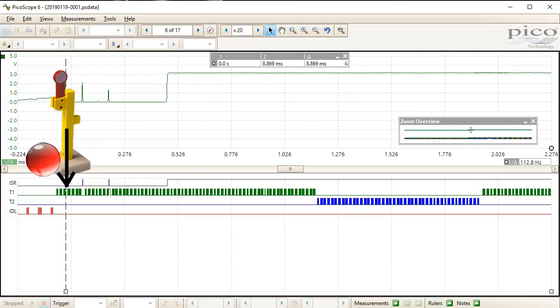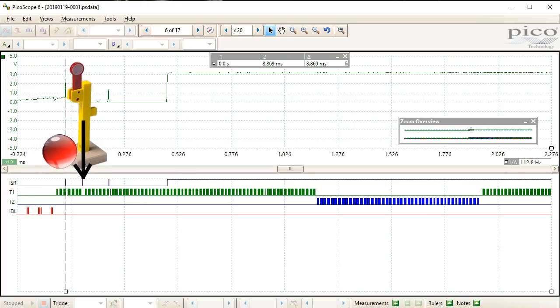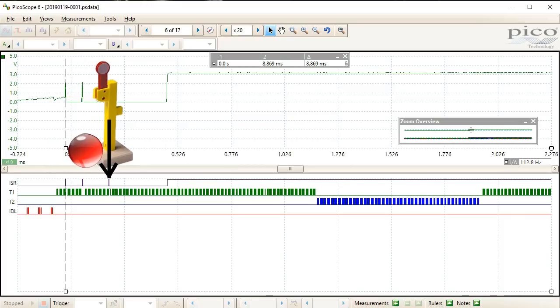Therefore, the wait operation was not performed and the token was not removed from the semaphore. The next falling edge caused the GPIO F interrupt to signal the semaphore, but this time the semaphore already had 1 token and could not accept another. The same exact thing happened by the third bounce of the switch as well.